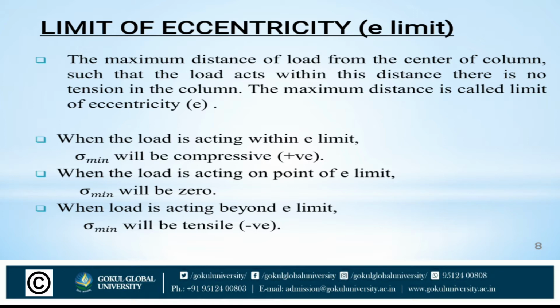When the load is acting within the limit, sigma min will be compressive, so it is positive. When the load is acting at the point e limit, sigma min will be 0. When the load acts beyond e limit, sigma min will be tensile, so it is negative.